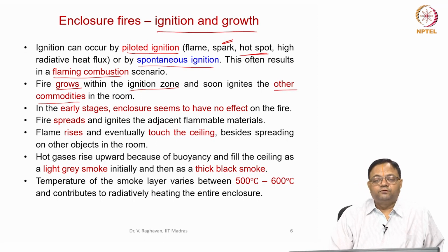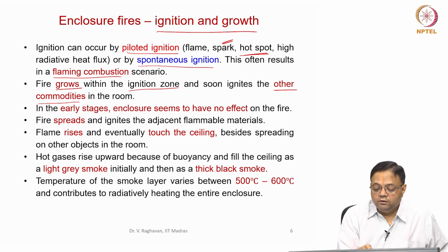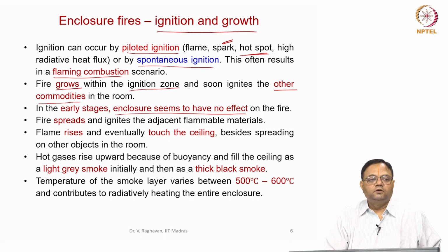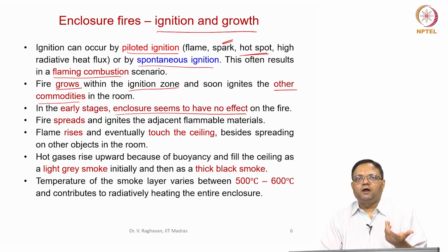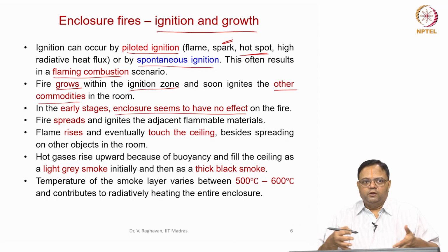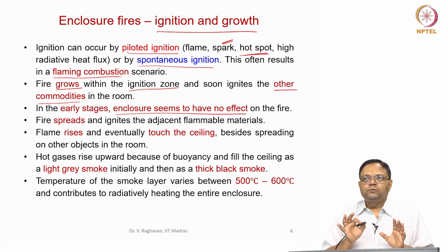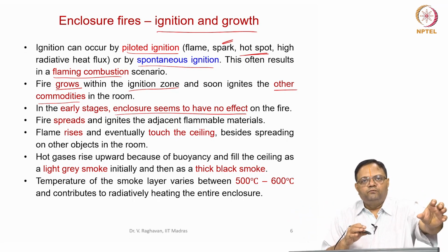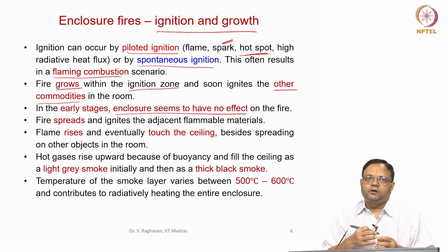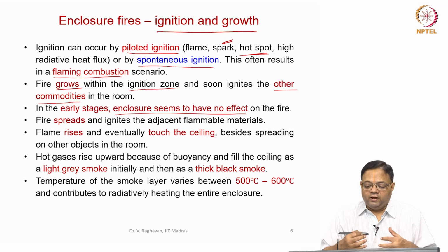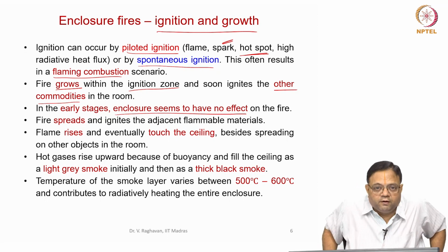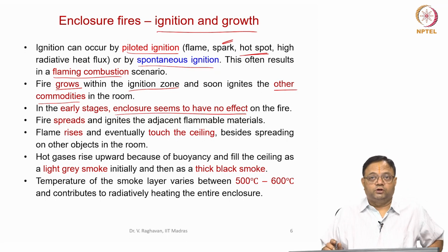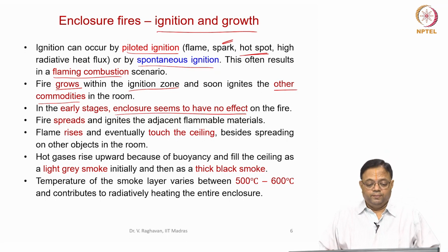In the early stages, enclosure seems to have no effect. That is, when a small fire is there, the enclosure conditions will not have any effect, because the enclosure has some oxygen. For feeding the small fire, this oxygen is more than enough. But as the fire grows or spreads, you will see that there may be an effect of the enclosure on the growth of this fire.